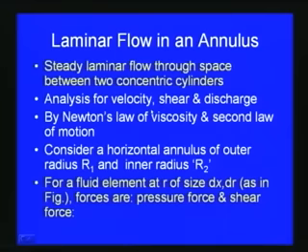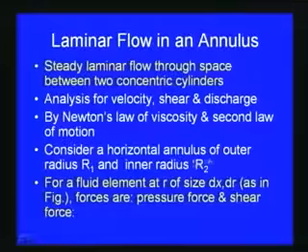Here also we are using the fundamental principle, that means Newton's second law. Here we consider a fluid element, and then we consider the forces acting on it, and since it is a steady state case we will be equating the forces acting on the fluid element to 0, and then we will be finding out the various parameters as we did in the case of laminar flow in pipes, which we discussed earlier. So, if we consider a horizontal annulus of outer radius r1 and inner radius r2, then here we will be deriving the equation for velocity and discharge and other parameters.